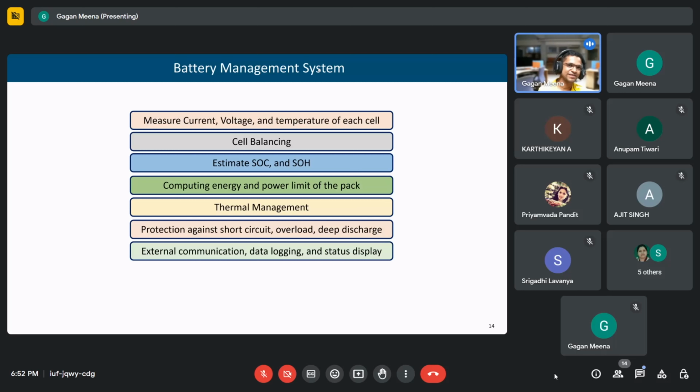Especially, what happens in most of the cases we have found is that once the vehicle is used, it is parked in sunshine. In daytime, when the irradiance is quite high, the battery is already heated because of driving, and then there is a further increase in temperature because of the surroundings, and the thermal management system is not able to cope with the increase in temperature, and then this problem happens. Because of this, several companies have changed their thermal management subsystem. Now these cases are reducing, but still we can find some of them.